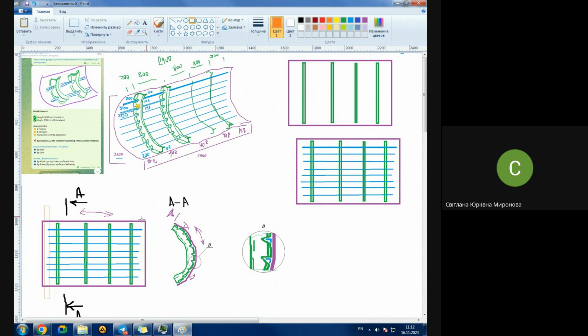Look, how many locators do we have if we assemble something by skin? 3 meters. I trust it's enough to have 3 locators. I said you, when it comes to locating by the outer contour, the distance between locators is typically no less than a meter, even greater. So for this rather short panel, it would be approximately 3 locators.